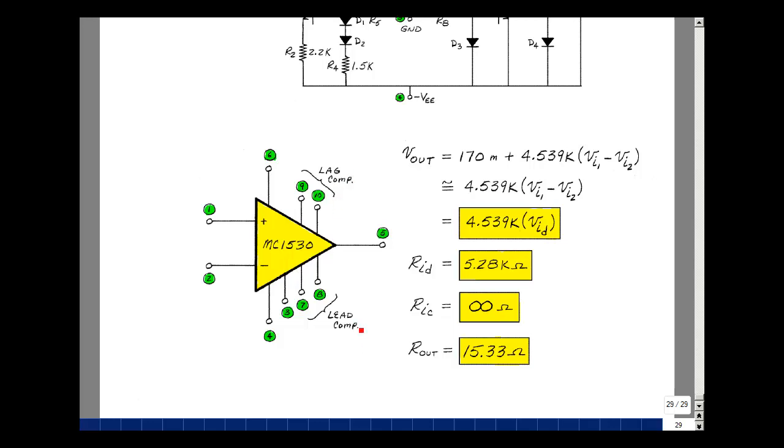What this is referring to is that if you put resistive feedback around this op amp, it may become unstable. And that's because these transistors and diodes have some capacitance, and when you put feedback around it, you can take the poles that are here, which are actually in the left half plane, and force them into the right half plane, and create an oscillator or a lockup condition. What we need to take a look at next is what is the capacitance associated with a transistor or a diode, and that's the material of Chapter 10. And this is the analysis of an MC1530 Motorola op amp.